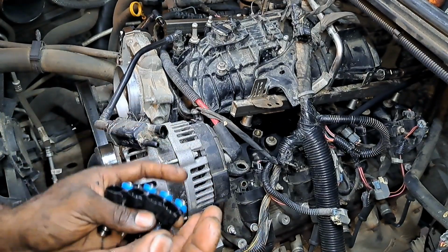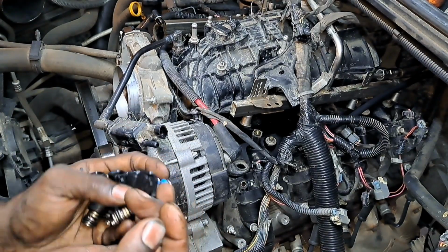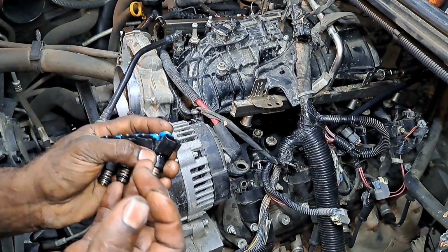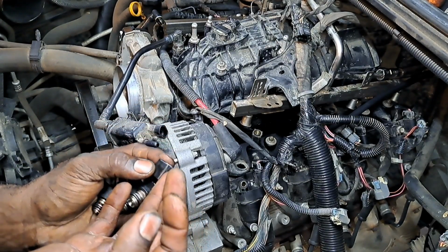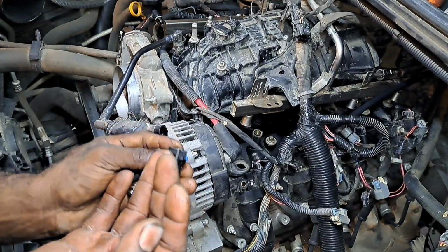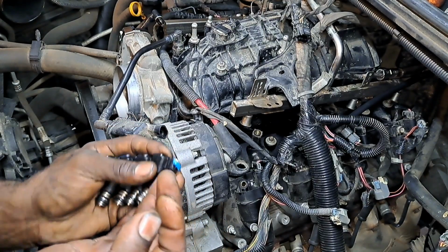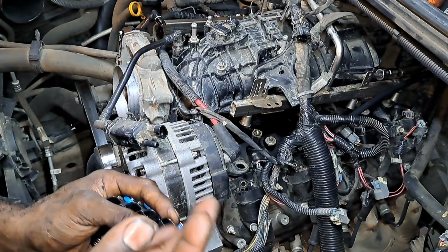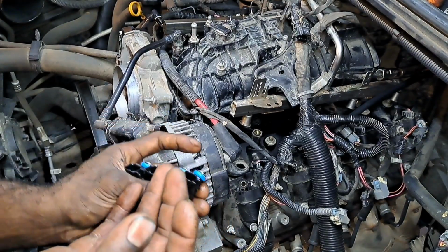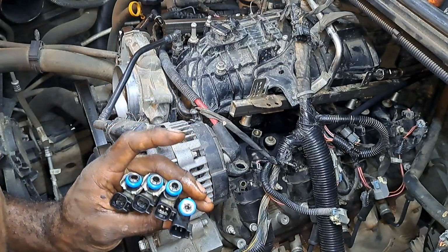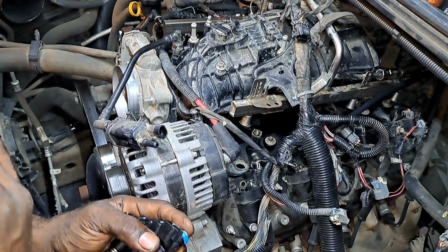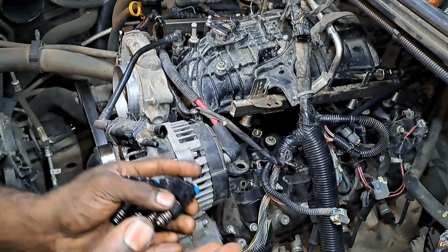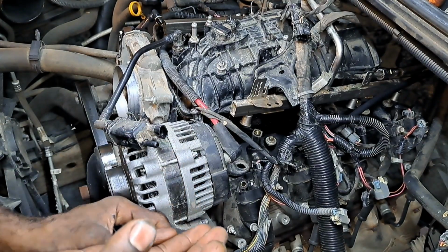And to be even more transparent, when I look back in hindsight, the Volvo, the Hondas and stuff that I did with the valve problems, you can do a fuel trim balance test, and it'll test the injectors. The 2018, 2019 Hondas were a lot more specific with the cylinders, but typically we would just replace all the injectors anyway. Unfortunately, it's going to be a little difficult to determine which one, but it's possible. If the car knows, you can find out.